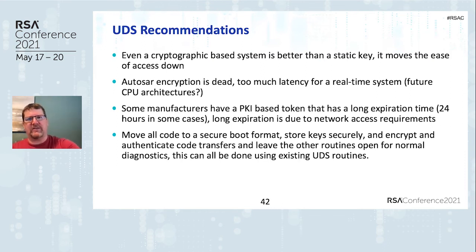I actually validated that the stuff running in memory and stuff stored in the hex files is the same value. So if there's a process to actually encrypt that, and then do a little bit stronger authentication on those code transfers, because the signature is actually just done upstream before it's pushed to the unit. And then just leave the other routines open for normal diagnostics. You can just do all this with existing UDS routines.